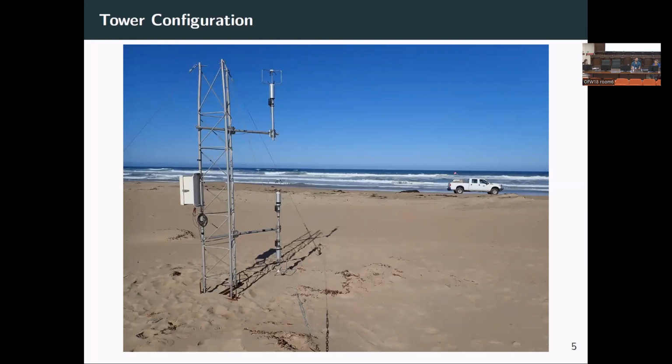I was able to visit the site to collect some wind data with sonic anemometers. This is a small tower that we were able to move around to various locations. In this case, this was collecting the boundary condition inlet data at about 10 hertz at 3 different vertical locations. We're unfortunately not able to do anything higher into the atmosphere because there's an invasive species that nests here, which is also a very contentious issue.